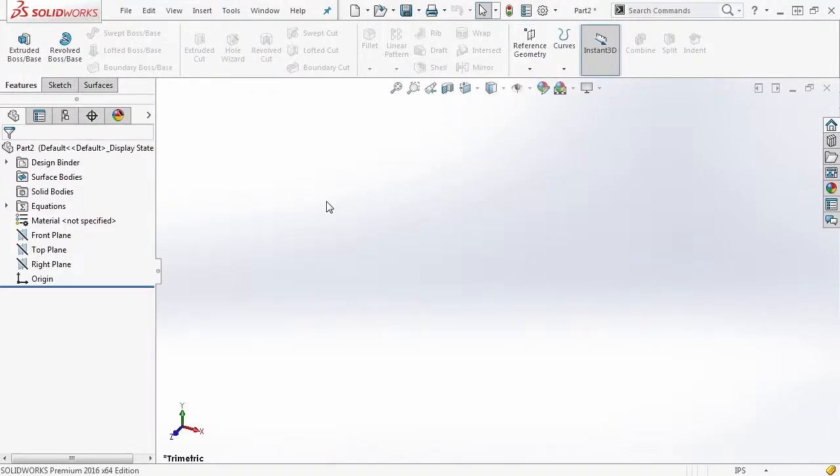We're going to follow a basic process to create this part, but I want to note before we get started that there's not a single way to do this part. We're going to create several different extrudes to create the geometry we need, then add a few fillets and things like that. But you could also create all of the geometry with a single revolve sketch. Because the revolve sketch is a little bit more advanced, takes a little bit more time, we're going to start by building upon it with individual features so that way you get comfortable with creating these features and applying draft and linking them to our global variables.